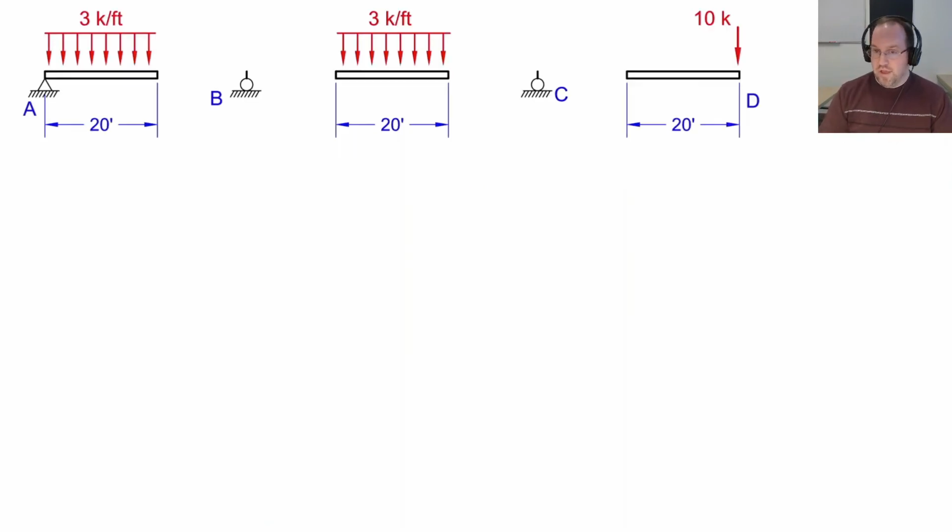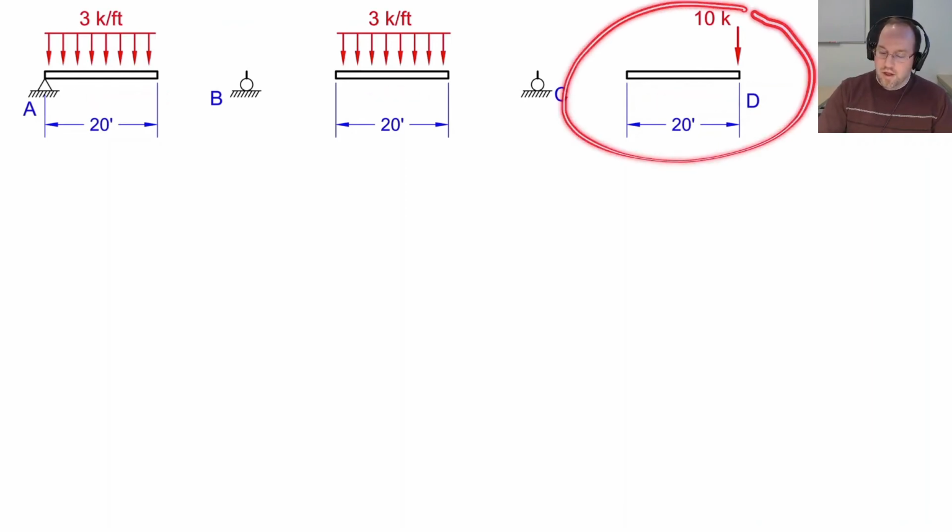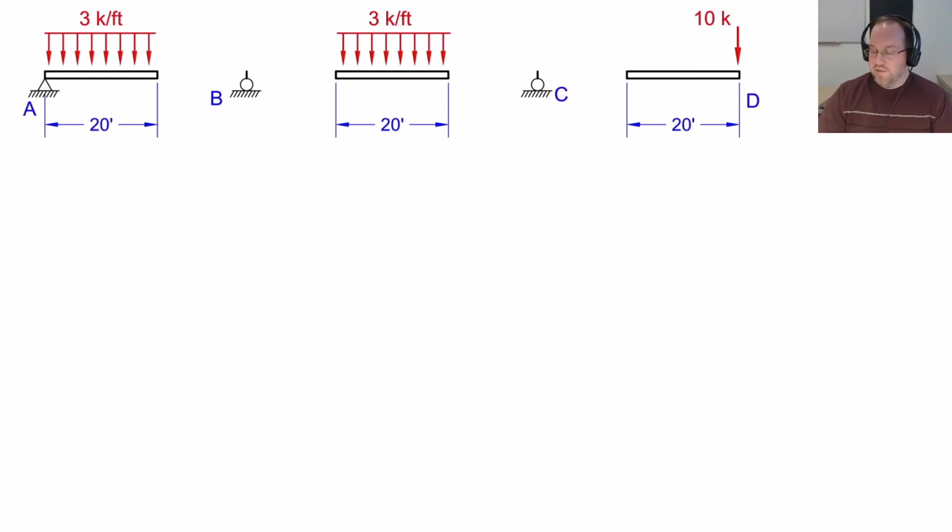So let's start again by breaking this up into its components. So I have 3 segments of beam from AB, BC, and CD. And I'm going to start with this cantilever end. And I'll show you the second shortcut that we can use when we have cantilever ends. The cantilever end is rather special because you know you have 0 moment and force here at the end. So therefore, you can just solve for this force using the sum of forces in the y direction.